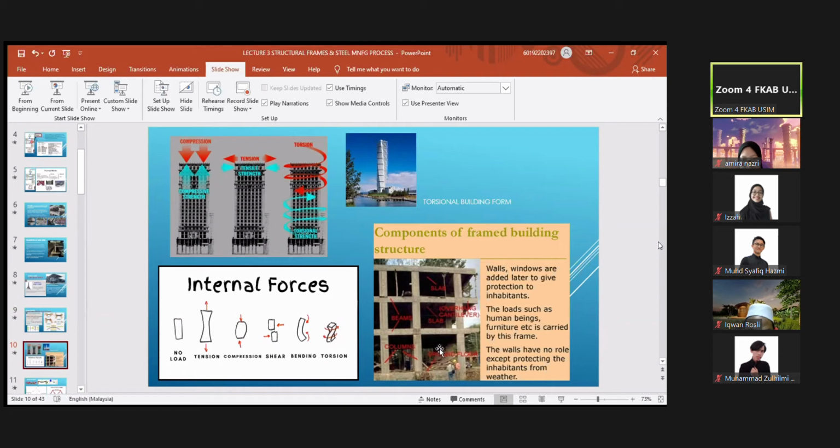But there are also cases where you can use such a frame, a steel frame, and once you fill it up with solid brick, engineering brick, that can become part of the bracing for the wall, so it becomes a rigid structure. If the wind force comes laterally, lateral load is wind load, it comes from the side, and then it cannot push it because it is so protected, made very rigid by the brick wall.